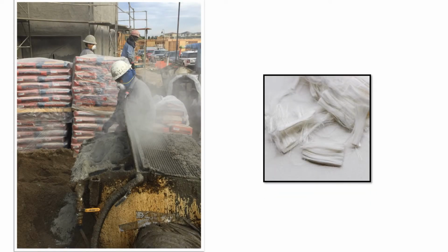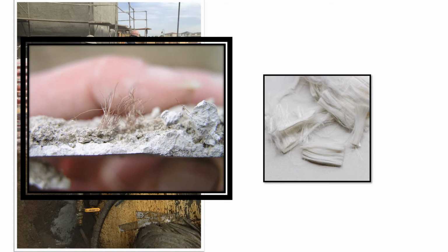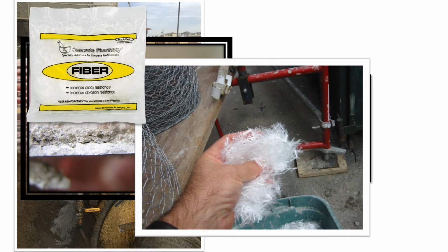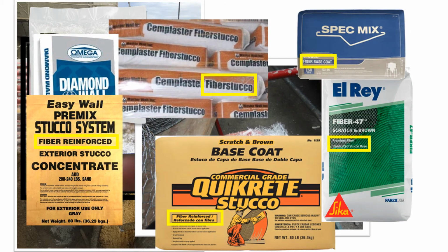Fibers have been proven to reduce shrinkage and cracking in cement and concrete for decades. The plaster industry has known about this for centuries and once used horsehair in plaster as a common practice. Today we use alkali-resistant fibers. They should be approved for stucco, and the SMA manufacturers produce many base coats with the fibers already in the bag. You should not add extra fibers to these blends.